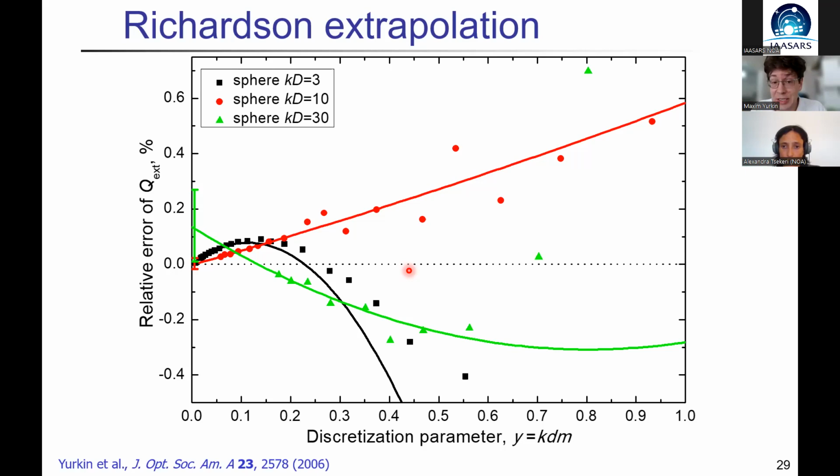If you want more confidence in the results, then you can look at something like that, as shown here. Basically you plot the results versus discretization and then do extrapolation. Where it crosses the vertical axis corresponds to more or less infinite discretization. Then you can use this value as an estimate of the exact result. And because you do this extrapolation by some least squares fitting, you also get some error bar, and that can be your estimate of your value. So that's one of the options to go.